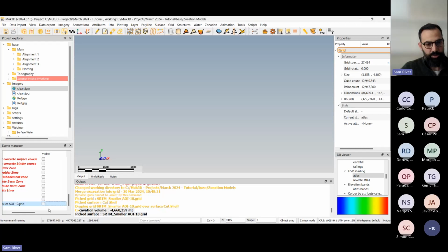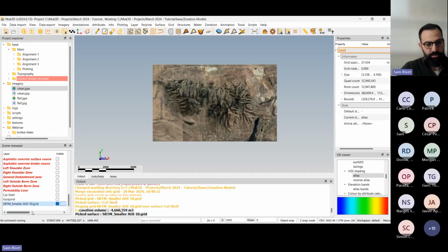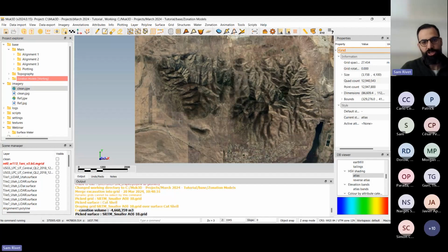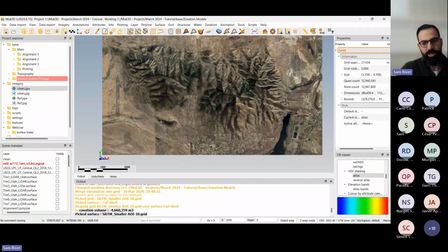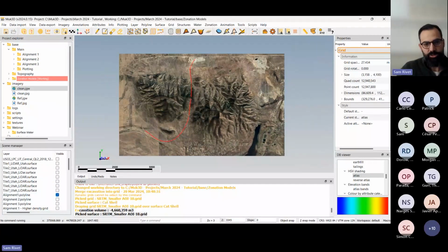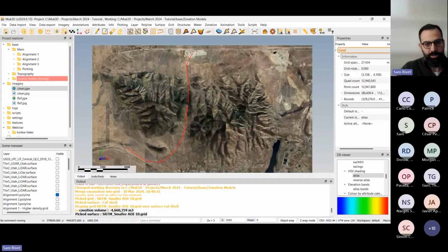So I'm just going to open my smaller SRTM surface again. And I'm going to use the information I'm getting from the picture and from the topography. We're just going to lay out 3 different alignments. Okay, my first one, I'm just going to come straight through here, and I'm trying to target this lower area in the mountains. Obviously, there is an existing road here, but that wouldn't be any fun. So, as a condition, I'm just going to try to cross these mountains with 3 different alignments.